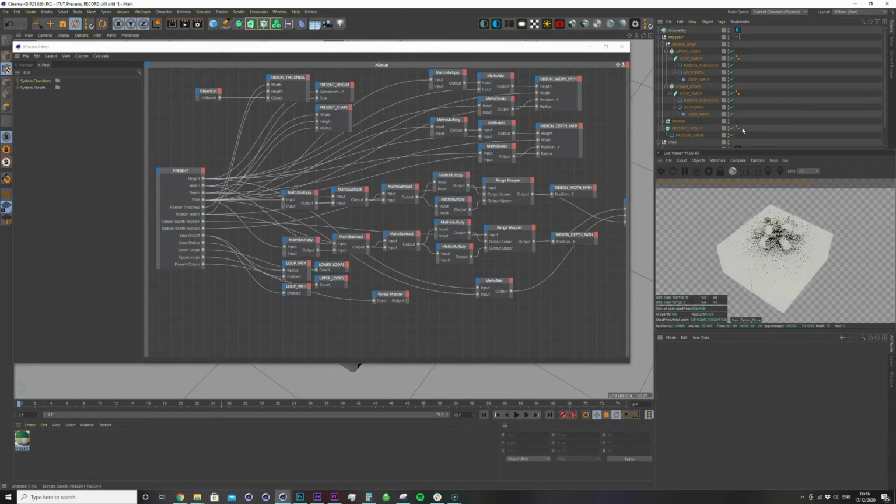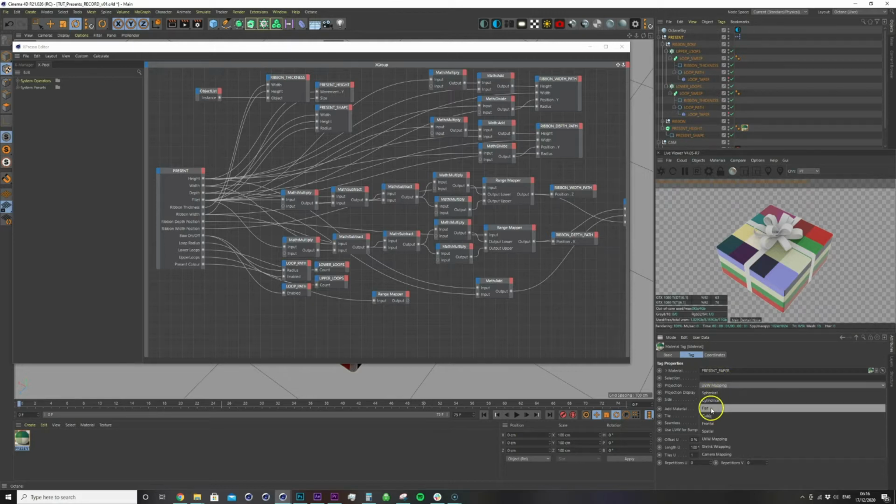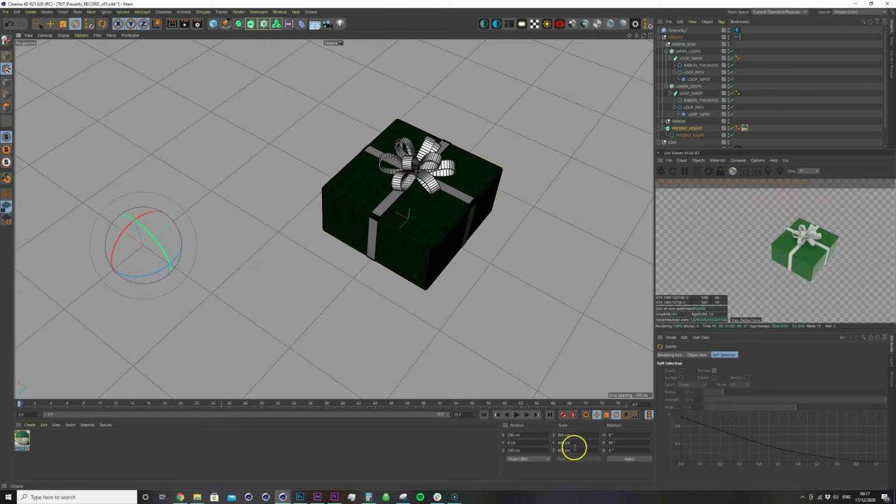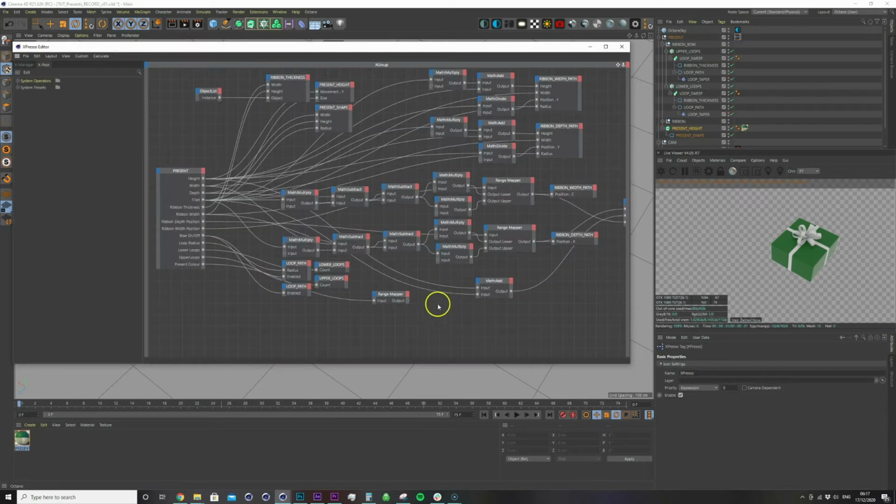So essentially what we do is we drag this present out onto the present height, and we change from UV mapping to flat. And we're going to change a couple of settings here. We're going to go X 200, Z 200, X 800, Z 200. We're going to apply that, and right now that is flat, and we're going to rotate it 90, and I guess we're going to go 800 as well. Okay, so 800 across the board. Actually, I don't think this matters. No, it doesn't matter. Okay, so we go into present, we have our settings, we drag this in, material, and offset U and offset V are the conditions we're looking for, and we're going to plug this into offset V.